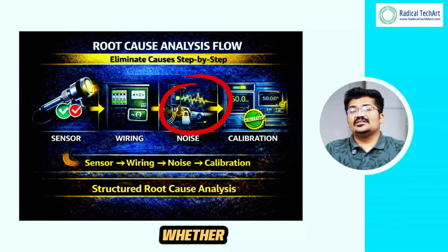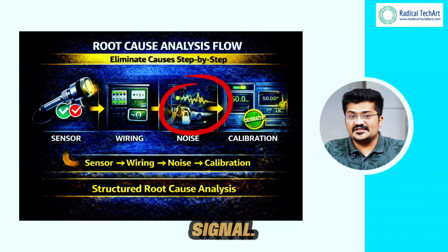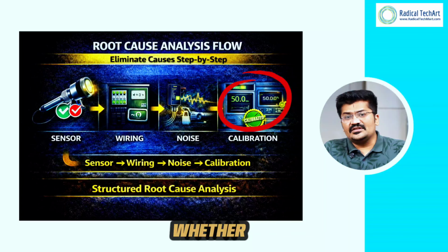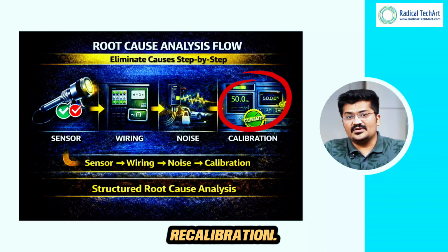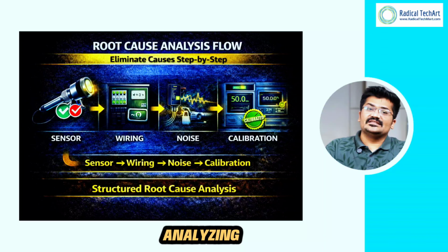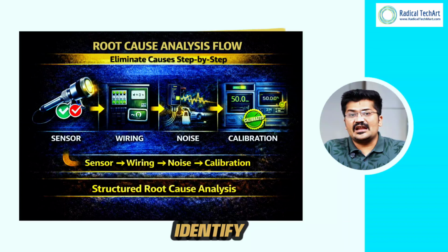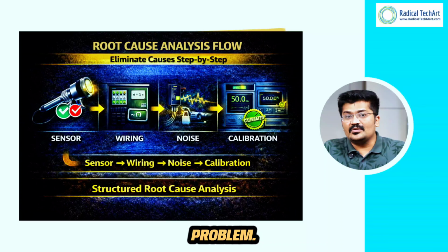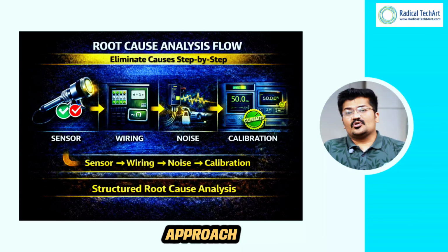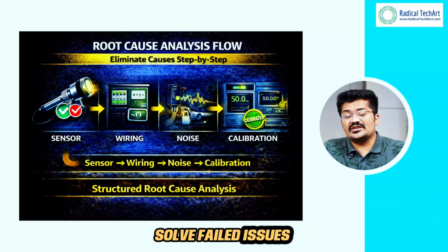Next, you verify whether there is electrical noise affecting the signal. Finally, you check whether the instrument requires recalibration. By systematically analyzing these factors, you can quickly identify the root cause of the problem. This structured approach helps solve field issues effectively.